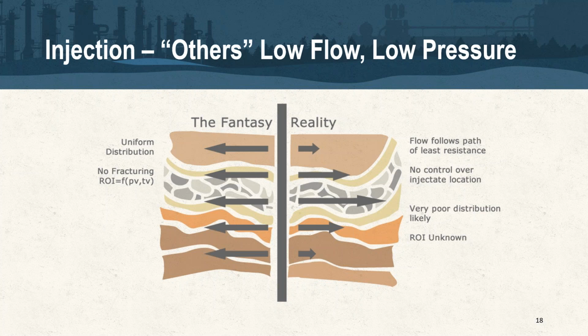A lot of times with conventional downhole equipment, you may be pumping into an open borehole. You may be trying to tremie the media into a specific interval. Even if a driller or other provider is using packers, they certainly don't have the type of pump we're discussing here today. And without that triplex pump, which I'll show you in a few minutes, it's going to be very hard to propagate your reactant into those zones and achieve distribution and treatment.